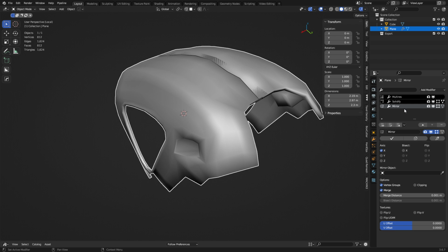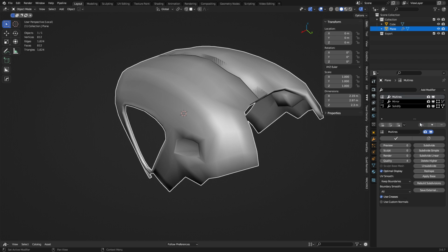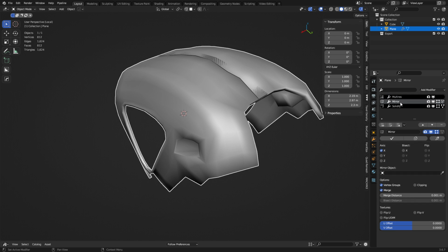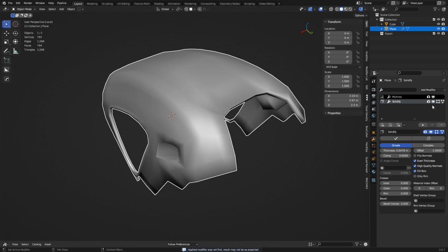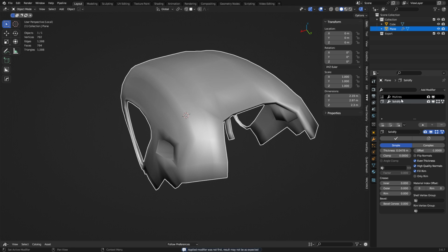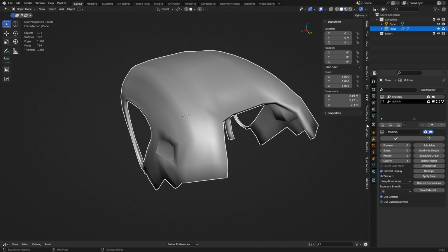And you can see the mirror take effect. The multi-res goes first, the mirror takes effect second. Kind of meh. So apply the mirror with a bisect. It's going to complain because the multi-res is in front of it. You might have to redo the multi-res. This can be a little bit finicky.